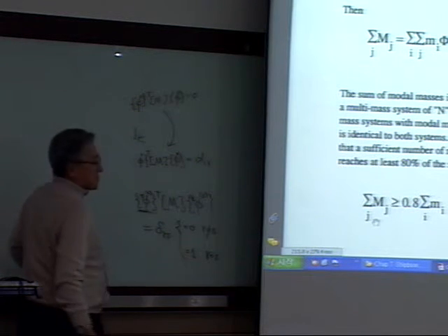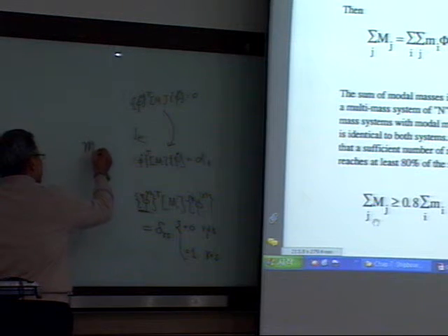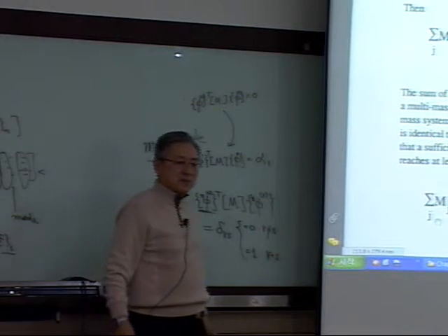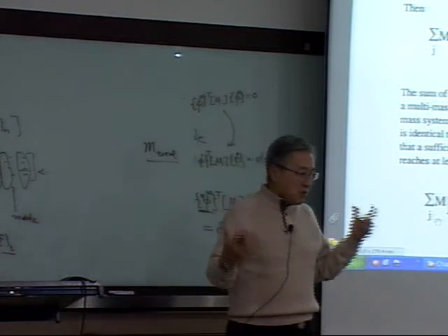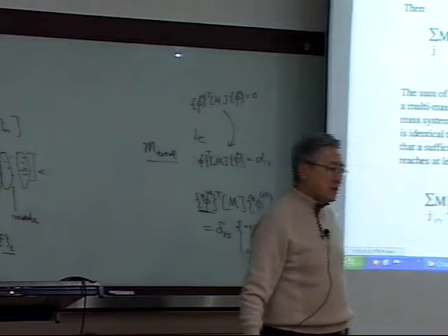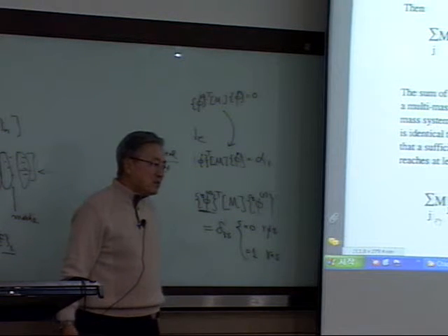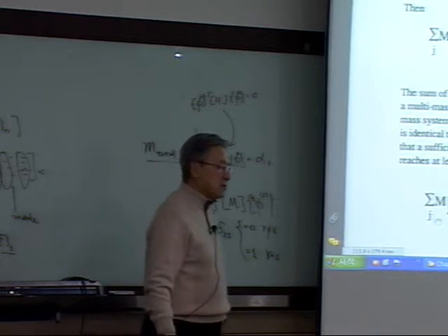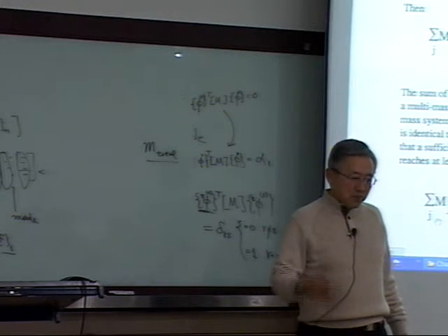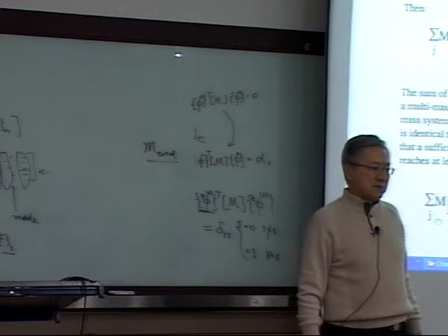After this section, we'll quit, okay? You know the total physical mass, right? When you're dealing with equipment, you know that total mass. Then my question is, in the analysis, how many modes do we have to use to generate the modal force in every mode, and apply that modal mass as a static loading to the system.